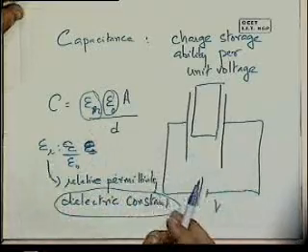So we talk in terms of K or epsilon. In different books, different notation is used, and you'll have high K materials, low K materials, which is very popular these days, even in the semiconductor industry, as the dimensions of the devices shrink, and so we talk about high K and low K. The same K refers to this epsilon R, which is the dielectric constant.